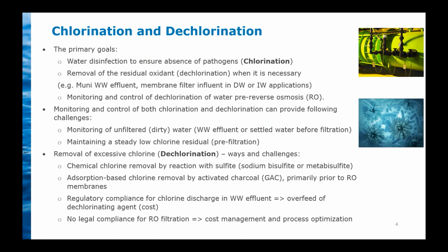Chemical chlorine removal can be done by reaction with sodium sulfite, bisulfite or metabisulfite. And here the underfeed of sulfite can cause compliance issues and fines, and overfeed of sulfite can lead to extra costs and anaerobic biofouling.